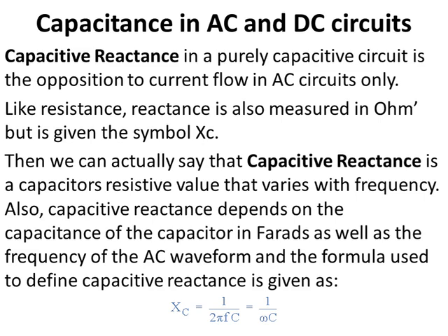The F there is frequency, while the C there is the capacitance. So in getting your reactance for a capacitance, your capacitance is very important. In some materials you can just see it as 1 over omega C. If you are not given omega, it is the same thing as 2 pi F. Omega is 2 pi F.